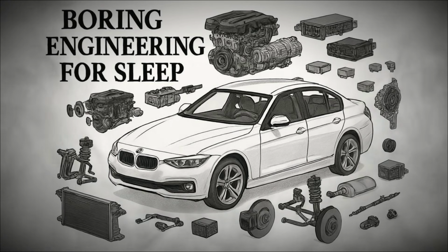A seatbelt restrains the occupant during sudden deceleration, preventing them from being thrown forward into the dashboard, steering wheel, or windshield. The basic three-point seatbelt, found in nearly all modern vehicles, consists of a lap belt and a shoulder belt, combined into one continuous strap, anchored at 3 points to the car's structure. This design spreads the forces of impact across the pelvis and chest, which are stronger areas of the body, reducing the risk of serious injury.